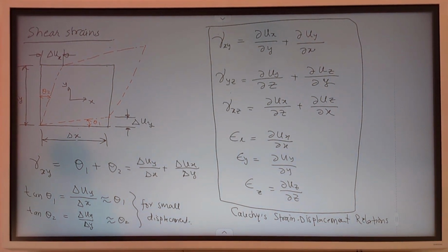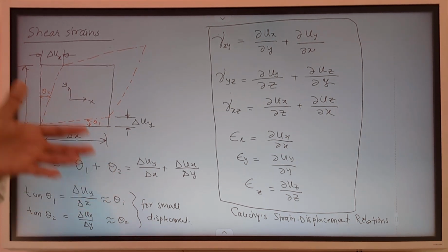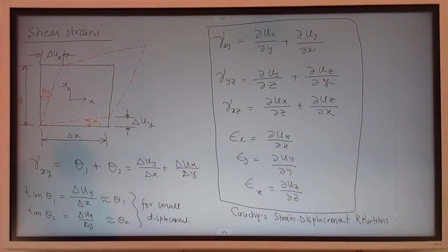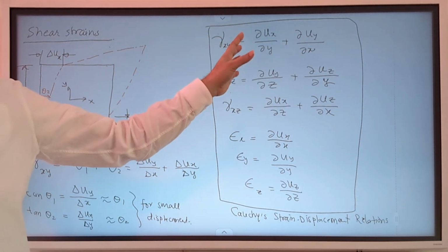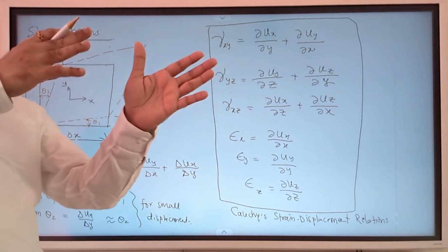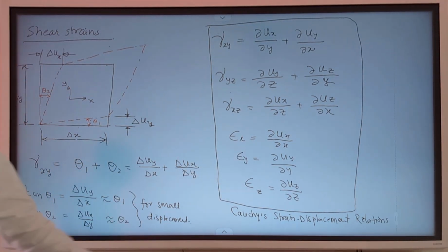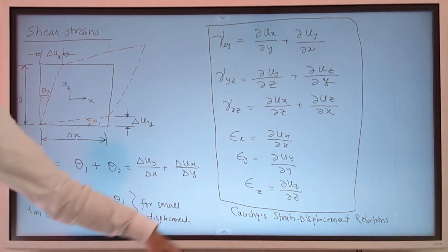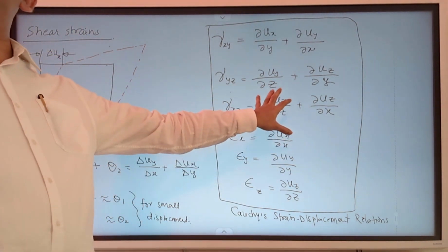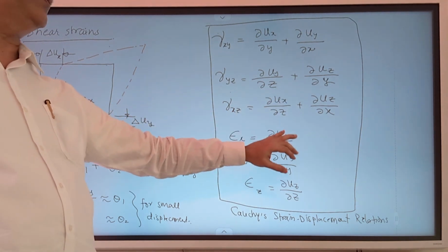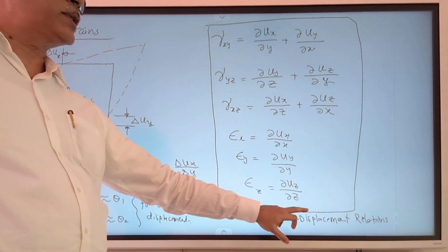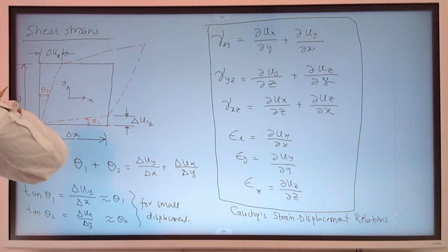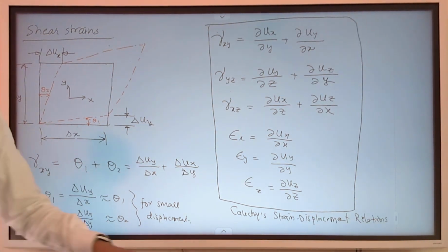So the general direction of analysis would be: first get the displacements either experimentally or through some numerical method. Then from that calculate the strains, and from strain you calculate the stress. So that is how routine numerical methods would work, and that is the utility of this particular equation. At the end of this lecture we will solve one numerical problem. Before that we will consider some other relationships related to strain analysis. So any questions at this point? So let's proceed.